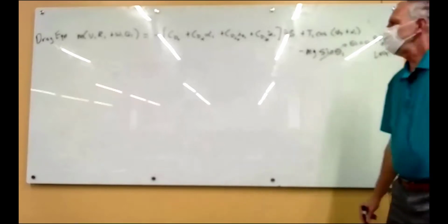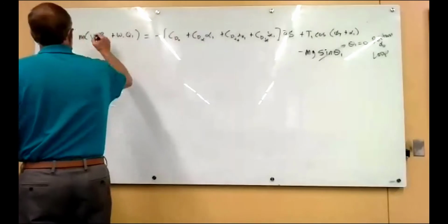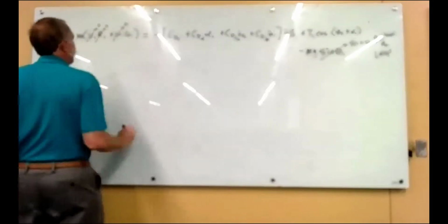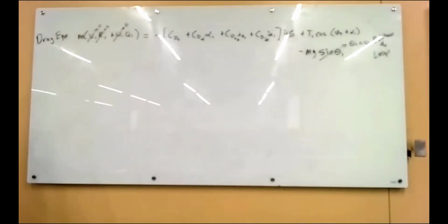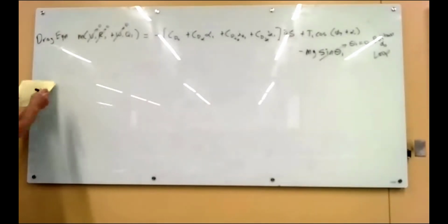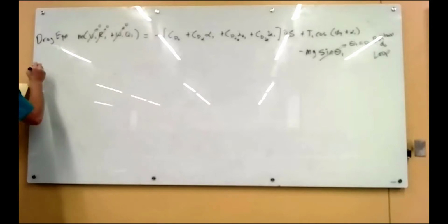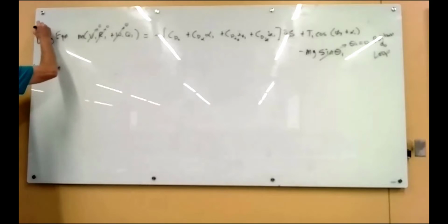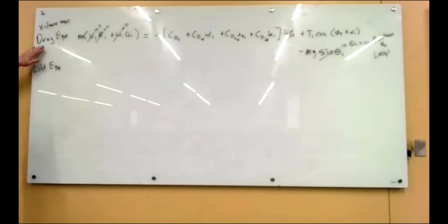So that's the drag equation. And we knock out V1 and R1. We're in stability axis, so W1 is 0. Then we got the lift equation. By the way, the other name for the drag equation, if we're in more general, this is the X force equation. It becomes a drag equation because in stability axis, drag is in the XS direction.